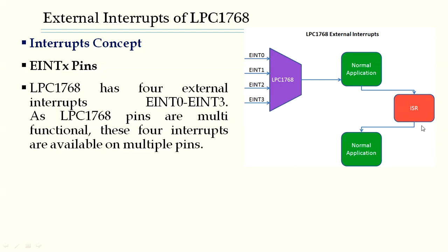So in the new context, it's basically the execution of the interrupt service routine that takes place. Once it finishes the execution, then it has to extract back all the registers, or rather we call in general the context of the main program into the current execution and start off executing from where it had stopped.